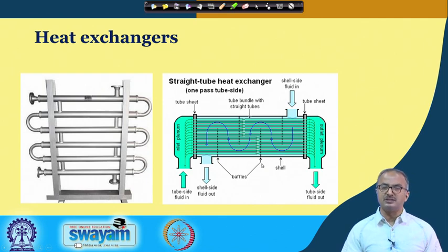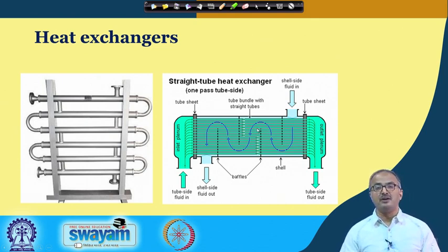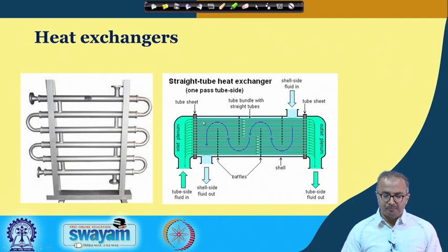The baffles have various reasons. One is to hold the tubes in place, and also these baffles affect the heat transfer between the two fluids. Okay. I am not going into detail of the baffles, because baffles have various types of designs, so that is not under the purview of this particular course. And these tubes are held at the two sides with tube sheets.